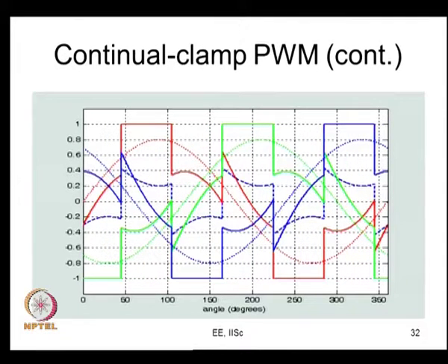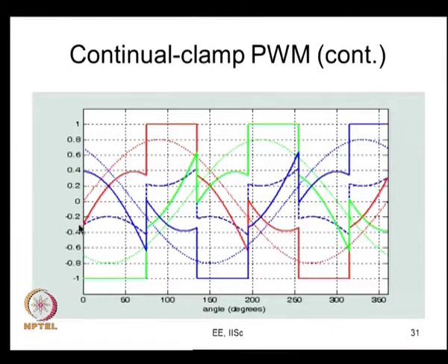Alright. So, depending on the power factor, you can vary your clamping location. As long as the load is lagging or leading and the angle is not more than 30 degrees, it is possible for you to clamp the phase exactly when its current is around its 0 crossing, for 60 degree duration around its 0 crossing. So, for example, here if your current is having its peak here, you can clamp it around 30 degrees before and 30 degrees after the current peak.